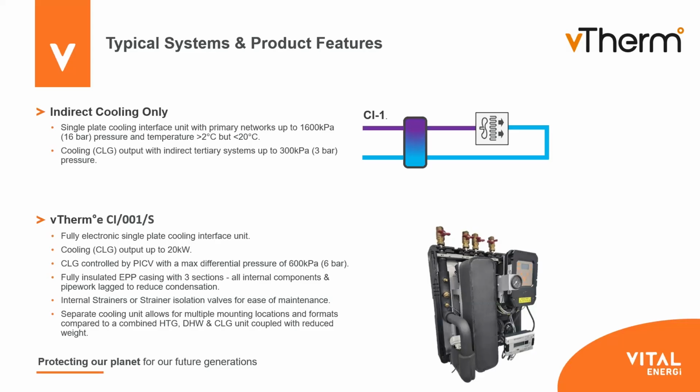One of the things that we've done with our HIU is we keep them separate. We don't combine them like other manufacturers may do. That has two effects. Number one, HIU is around about 35 kilos. CIU could be 45 kilos. And if you have that as a joined unit, you've got a lot of weight there to try and install, first of all. Also, the pipework is being blended together. The other thing is, you're then restricted where you can mount HIUs and CIUs. So if they're separate units, you can put them top and bottom, side by side, or even in different locations altogether.